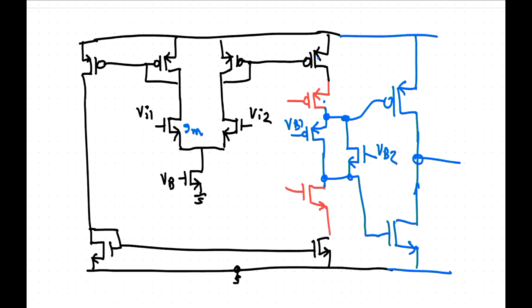They're still depending on the impedance in the 2 output branches of these current mirrors. So you don't really change what happens on these nodes as such in terms of what the voltage swings are. Well, what you do change is where the bias points lie, because you can choose the voltage here by this bias voltage. So the voltage bias on the gate here, you can choose it to be anything really, just as long as you keep these 2 in saturation.